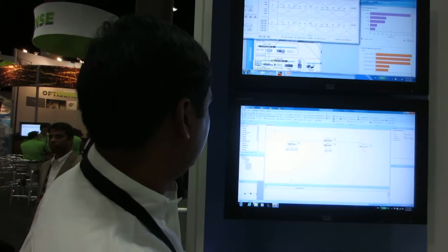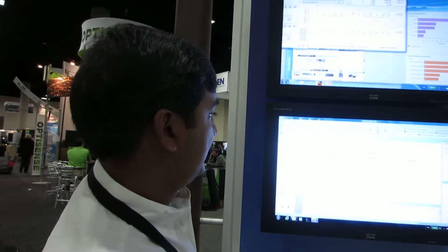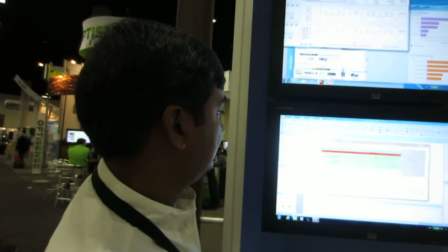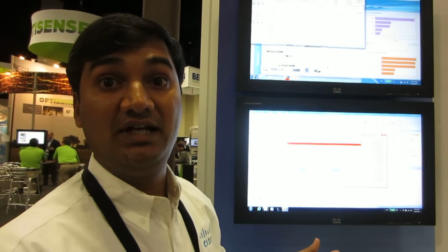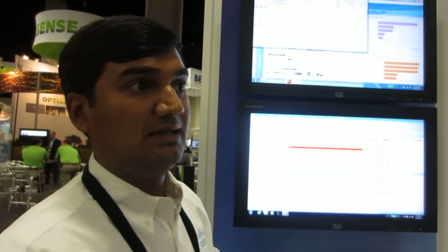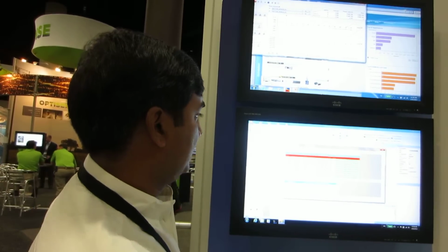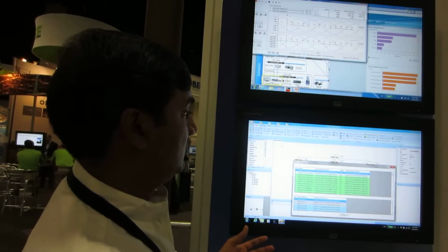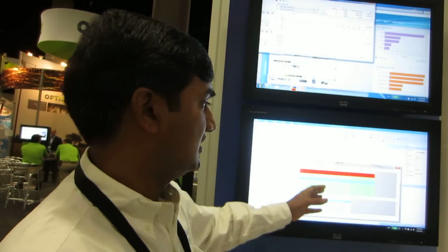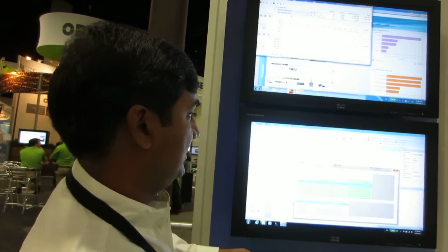What we can also show you is, once you have the IEDs and all the information is flowing through our switches, we can capture all the information. Previously it used to go through all the copper wires, but now it's all through the switches. Once it goes into the switch, we capture all the information and persist it, and since we have the data, you can do a lot more. You can see this IED and also see what GOOSE messages are going in and out of these IEDs, which was never available to you before. So it's not only about cost saving, but it also enables a lot more features and capabilities in your substation. This tells you the GOOSE messages going in and out of this IED, the critical messages, and you can also act upon them.